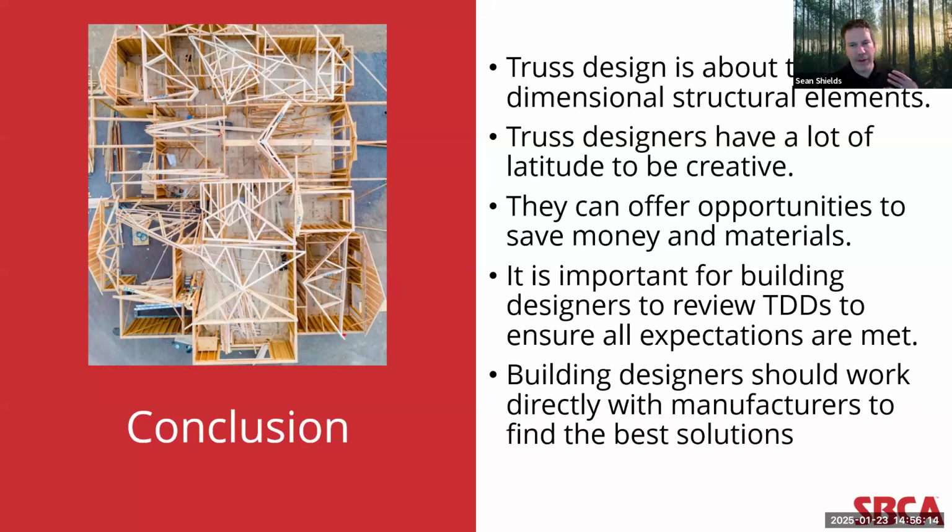And the truss design drawings graphically illustrate each truss in a system for the building designer and for the building official and for the framer to easily inspect it, do a review process, and understand how that truss is supposed to function and be installed. But hopefully, this presentation has made it clear that the truss designer has a great deal of latitude in determining exactly where those determined loads are transferred through a particular truss.